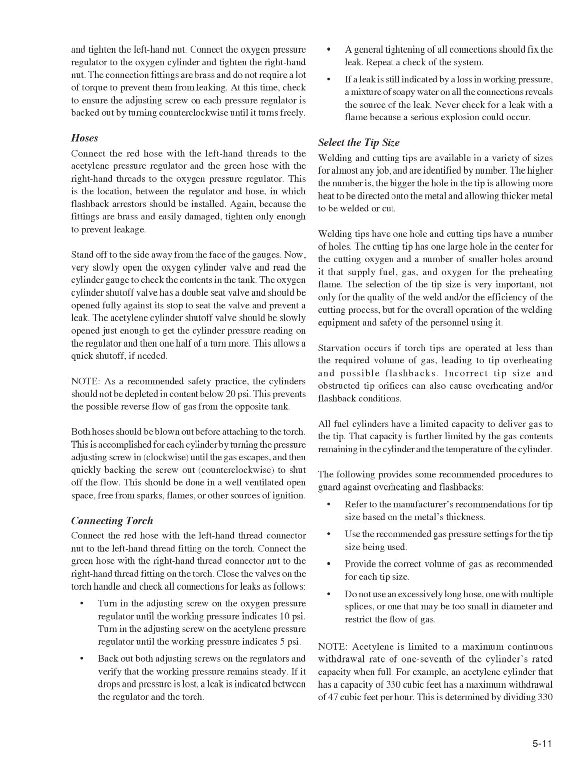The following provides some recommended procedures to guard against overheating and flashbacks. Refer to the manufacturer's recommendations for tip size based on the metal's thickness. Use the recommended gas pressure settings for the tip size being used. Provide the correct volume of gas as recommended for each tip size.